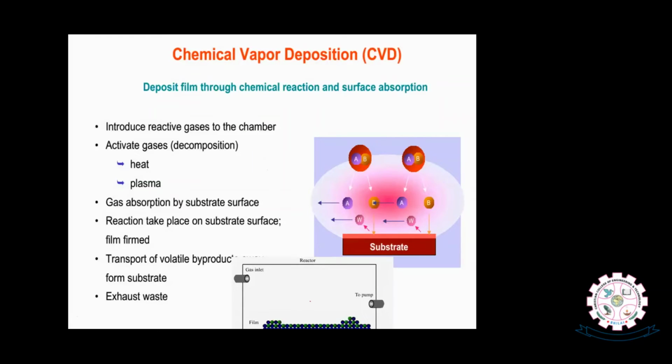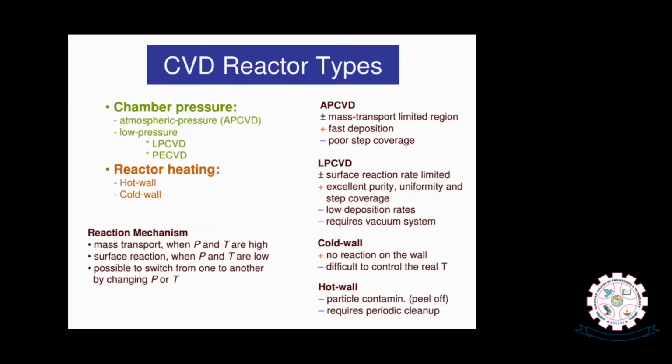So you can see how the film is deposited in the case of a CVD. See, the gases are coming here, whatever gases, and there is a pump here to create a vacuum, and there is a substrate here which is heated up. See, diffusion of precursors is occurring here, and you see they are trying to form a layer. Surface diffusion is happening here on the surface.